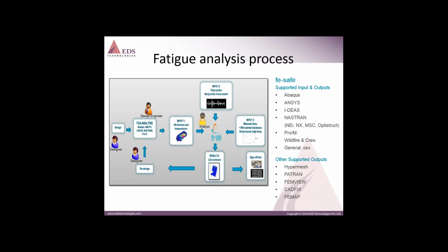This is a typical fatigue analysis process. You can see here is where FE-SAFE fits in. You have a designer who gives the preliminary design, and the FE analyst is the one who analyzes it. You can use Abaqus, ANSYS, or I-DEAS for your FE analysis, and this FE analysis result will be one of your inputs for FE-SAFE.